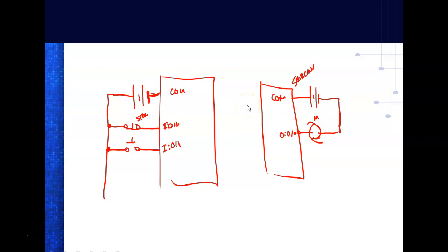And what we'll probably let y'all do, once y'all get on into them, is use this box right here and actually wire up the output. We're not going to now, but it would be just like I hooked it up here. I could take this common here and run it down to here, and then I could take this wire right here and run it up to there. What's nice about this trainer is you can wire a PLC without actually wiring the PLC, using banana plugs, which makes it real convenient.